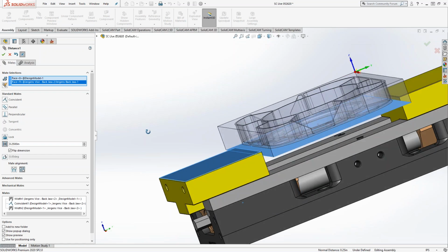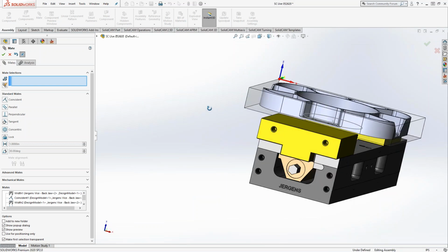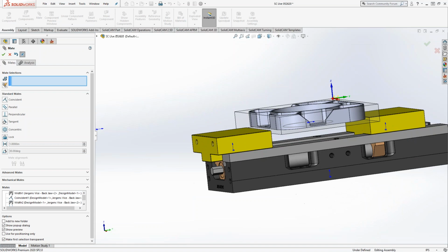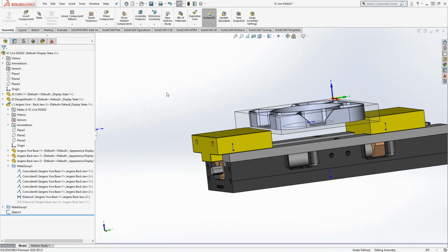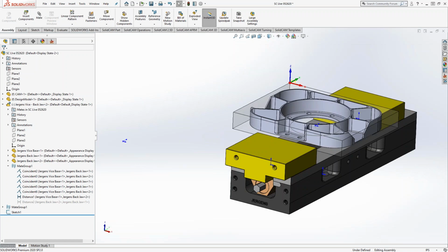Now, Brian had a good point as you're kind of still mating up. What Brian does with his setup is he'll just do his jaws only, because that's the most common thing that you will run across, especially in a simplified 2.5D application here. If you guys start getting into 4-axis or simultaneous 5-axis, then definitely include everything in there. But yeah, it's a great point, Brian. Save up some assembly time and some component loading time as well.